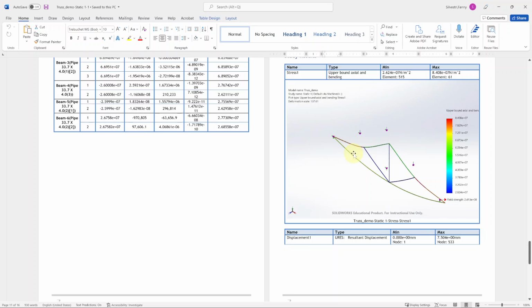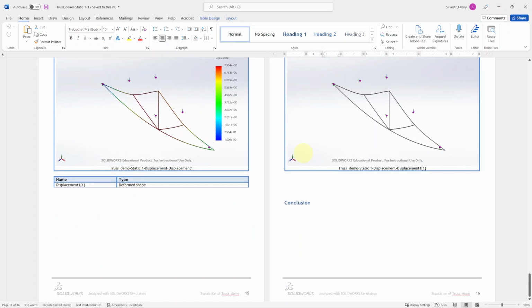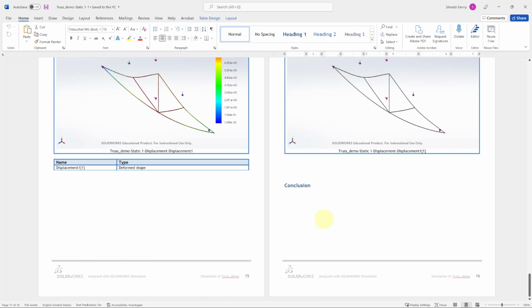What I look when I open your report is that it's symmetrical, that's you have the same color on each member if you apply a symmetrical load. If the load is not symmetrical, it will not be symmetrical, but in that case, it should be. So yeah, you have different value, and you can edit the document and add information to it. So I hope you find this helpful.